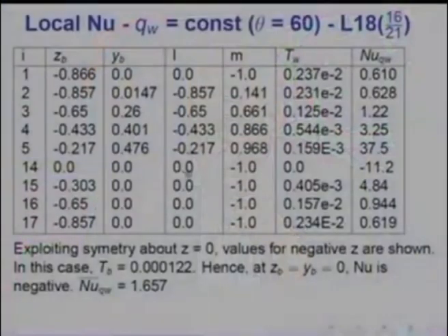This is of great consequence, for example, if the corner point also is a highly stressed point, and if it has very high temperature with very large temperature gradients around that point, there could be cracking or thermal warping or anything of that kind. So, solutions of this type are essentially meant to discover hot spots along the wall. As you can see here, at all the points that I have shown, those points close to the corner are very high temperature.